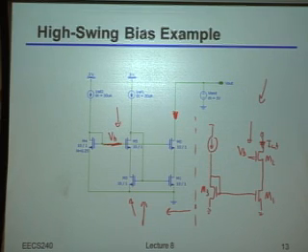So the more technical explanation is that if you went to this kind of structure here, now this drain voltage is much more likely, in fact almost guaranteed, to be the same as this drain voltage, because now the cascode is actually forcing those two drain voltages to be the same. Whereas in this case, that drain voltage is whatever the gate to source voltage is, which by no means is going to be the same as what this point here is. Okay?